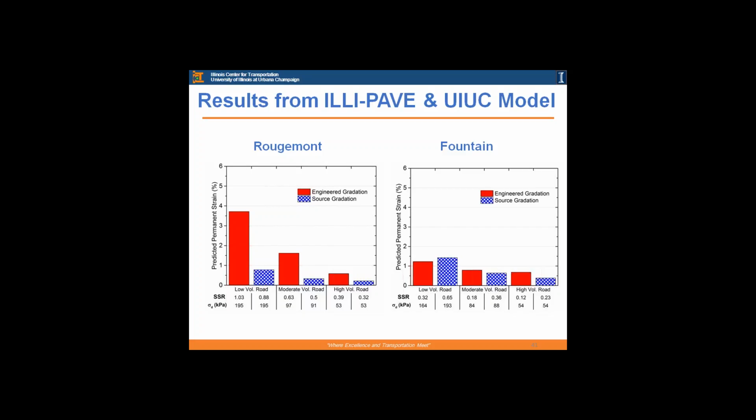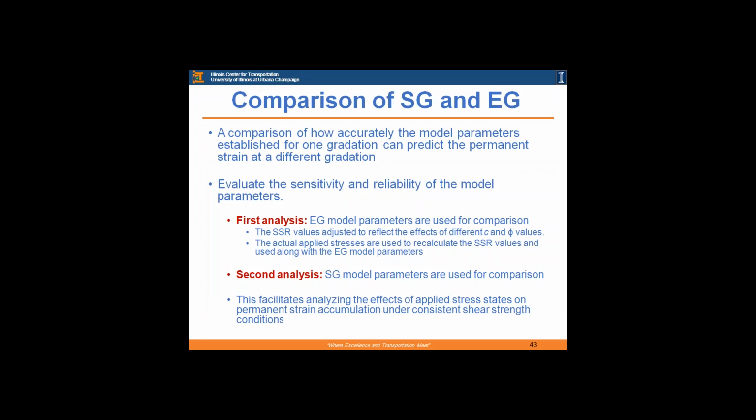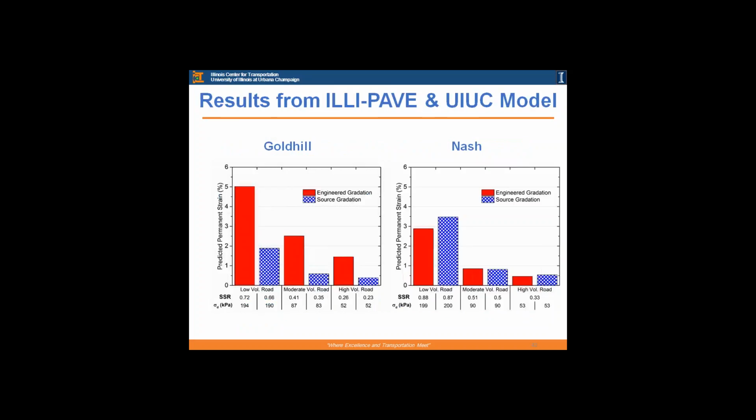How much stress is coming on top of the subgrade, for example, as a subgrade rutting model. If you think it's just strain-dependent, the strain values in the different models, if you look at the Asphalt Institute, Shell model, TRL model, they're all over the place. Stress is much better to control, and I think that's the reason why more and more recently the work with Carlos Gonzalez, who finished his PhD last May, at the Army Corps of Engineers lab, ERDC down in Vicksburg, Mississippi, their airfield pavement division, they're shifting to using that more.